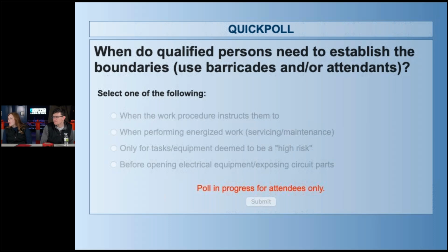And we have a question here. Is there another way essentially to figure out what PPE to wear other than voltage and energy calculations? Not really. That's the only acceptable method to determine what PPE is required within those boundaries. Also, to figure out what those boundaries are, you need to know the nominal voltage and have some kind of arc flash analysis performed. Per the 70E, there are two methods that have been recognized: the IEEE 1584 calculation method of finding the incident energy, and there's also a tables method. It still requires you to know a lot of information to apply it properly though.